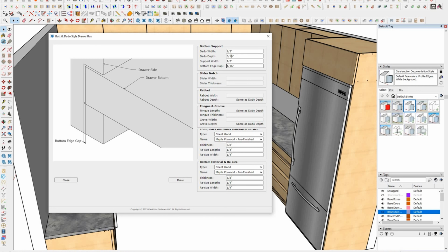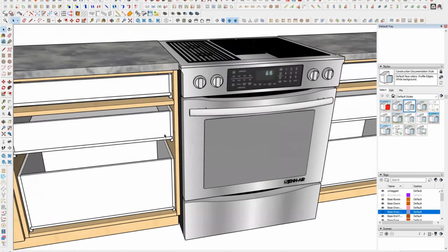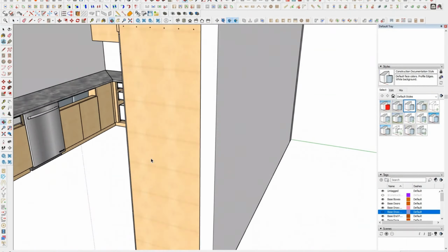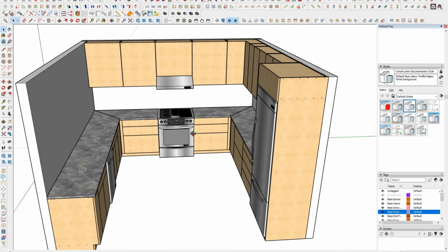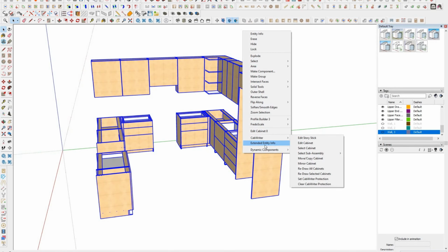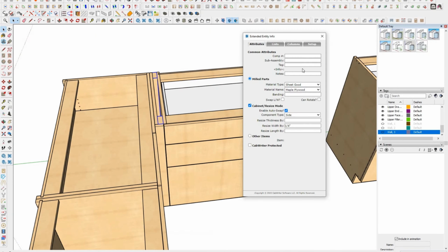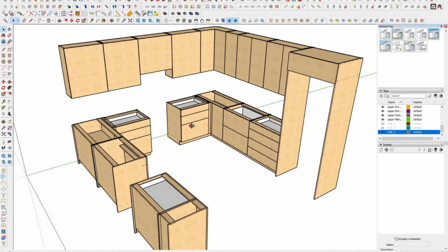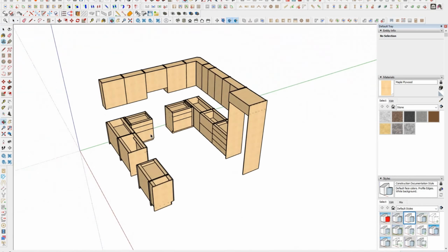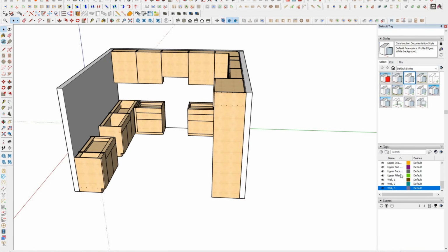So right here now, I believe we are not going to buy pre-built drawer boxes. So again, I'm making the drawer box parts here. I'm using 1/2 inch for the drawers, and for the drawer slides, if you have a specific brand that you want to use, we can update the space that we leave between the drawer sides and the box sides, so the drawer sides can fit well.